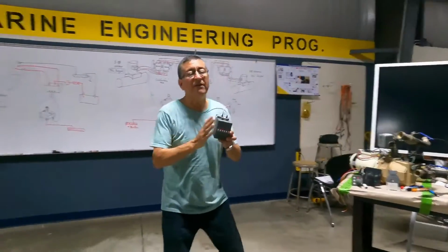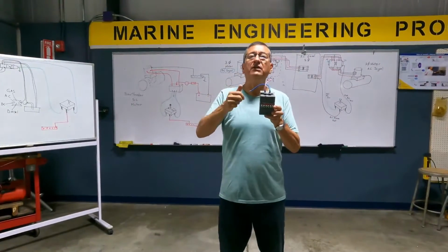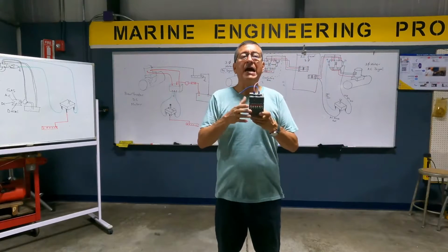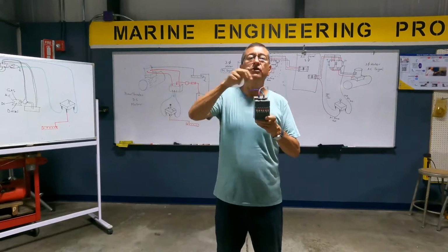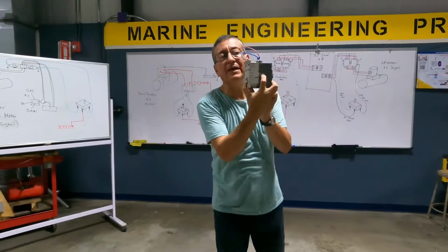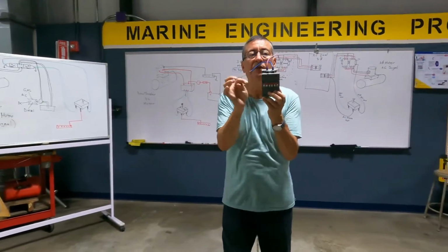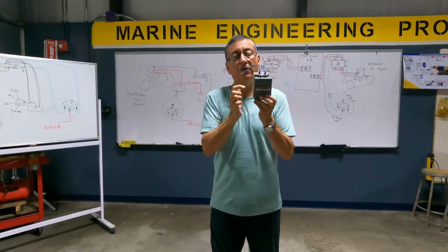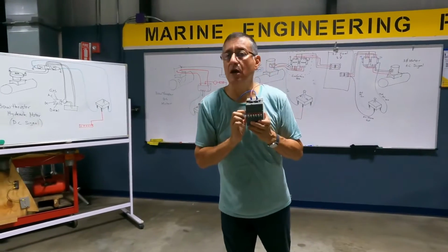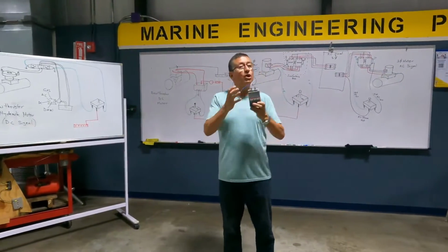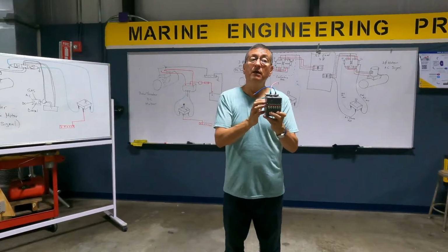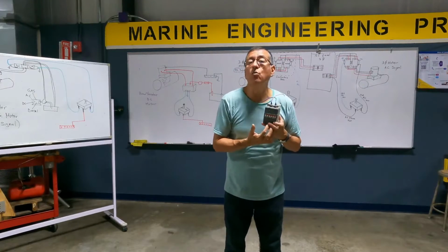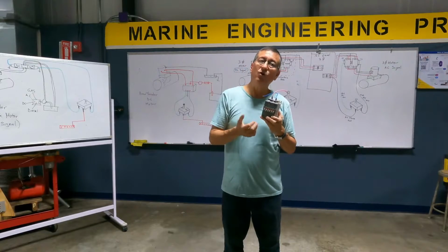Mr. Lopez, if I have 2 contactors together, one to activate up and the other to activate down, how can I avoid that people activate both of them at the same time? Because they have a plastic element between both of them to avoid that you activate both at the same time. The name of that link is the interlock. You order this breaker according to the capacity in amps and according to the signal that you want to activate, AC signal or DC signal.